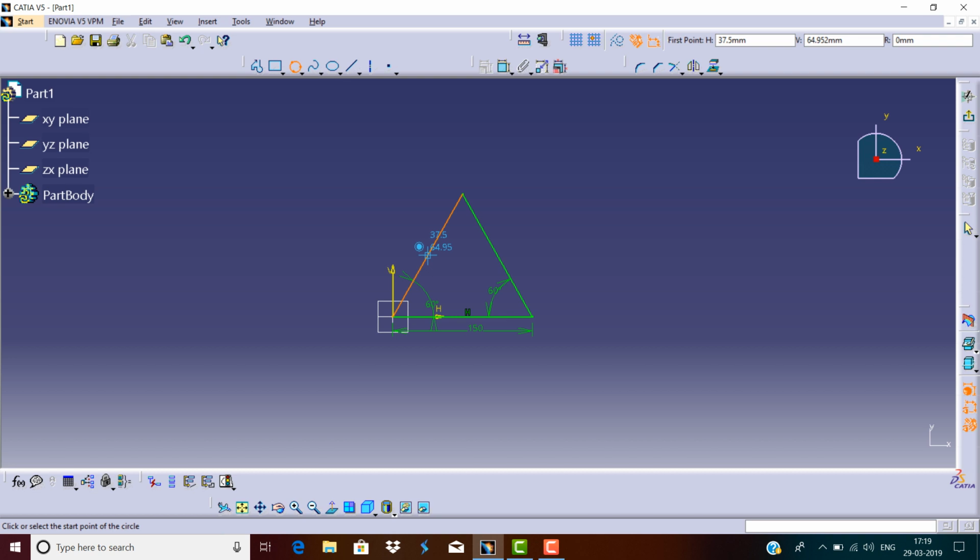So this is the major difference. You can tell it when you hover on the line. The circles are concentric and hollow, and when you come to the midpoint of the line, the circles are solid and concentric. So I just pick any of these points, anywhere, and I can define the 3-point circle. Just click here. So this is your circle, which is defined by 3 points.